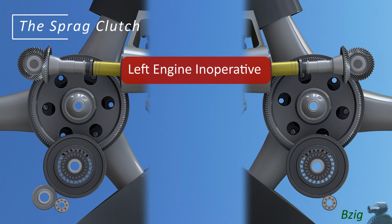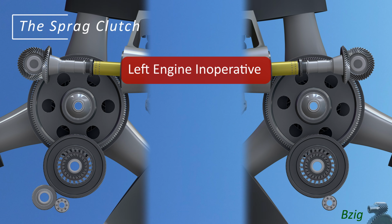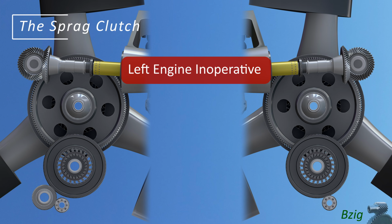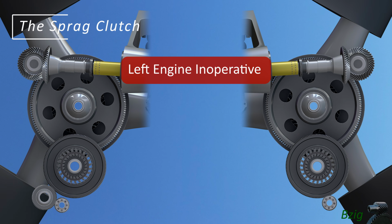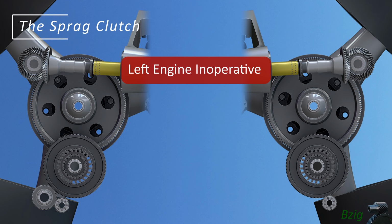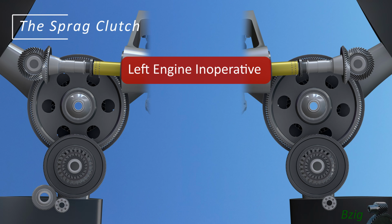In fact, I keep talking about engine failure, but it's not actually necessary for the engine to fail for the clutch to overrun. All that's needed is for the prop rotors to turn at a faster relative speed than the engine. It's not all that common, but it is possible in both helicopters and tilt rotors to go in and out of clutch engagement during aggressive maneuvering flight, even when the engines are operating.